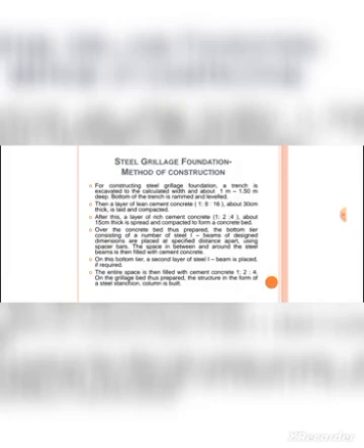Over the concrete bed, a bottom tier consisting of a number of steel I beams of designed dimensions is placed at a specified distance apart using spacer bars, and the space around the steel beams is then filled with concrete. On this bottom tier, a second layer of I beams is placed, and the entire space is filled with concrete of the proportion 1:2:4. The grillage is formed in a grill-like pattern. That is why it is called grillage foundation. On the grillage bed, the steel stanchion column is then built.